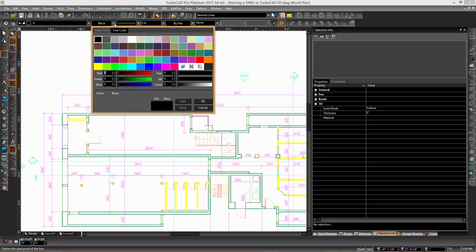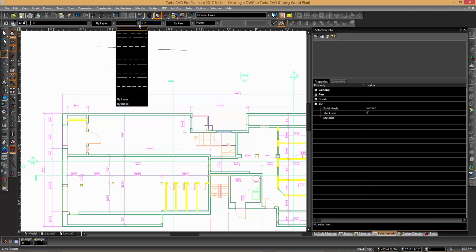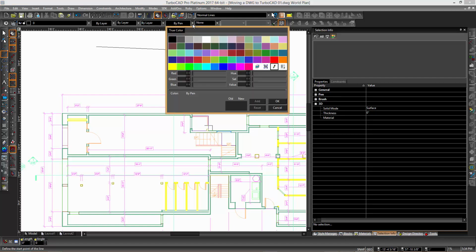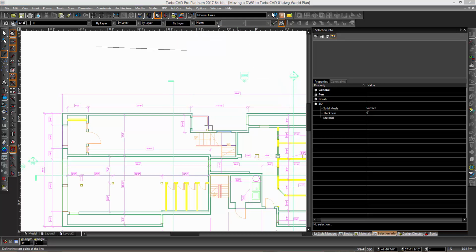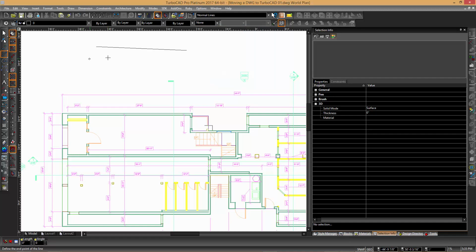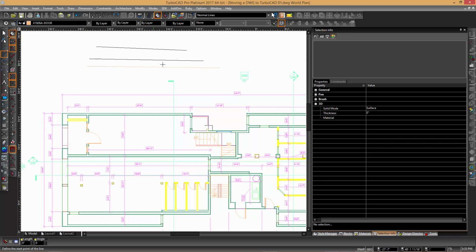If the line tool is selected and we have not yet started the drawing operation, any changes to the property pull-down or Selection Info palette will allow you to change the default properties of that tool. We see that you can choose the option by layer available in each of these drop-down selections. The brush pattern offers additional functionality that is not available in AutoCAD unless it is specifically a hatch entity. For now, we will leave the setting as none. Now we choose an alternative layer and draw a new line, and it takes on the settings of that layer.